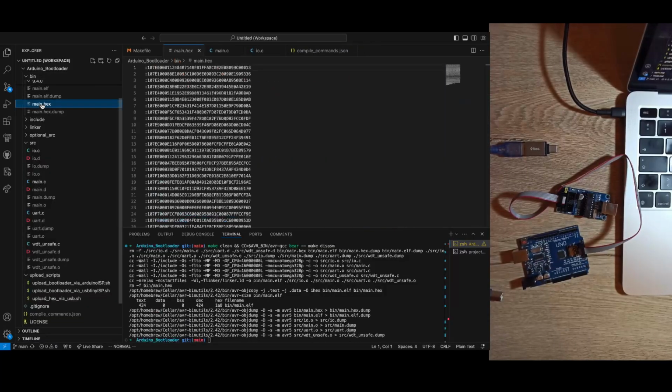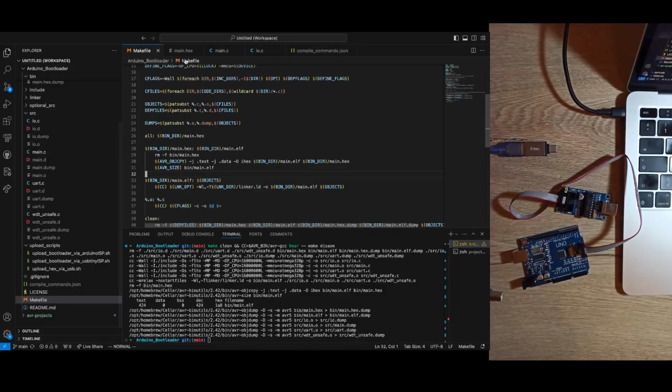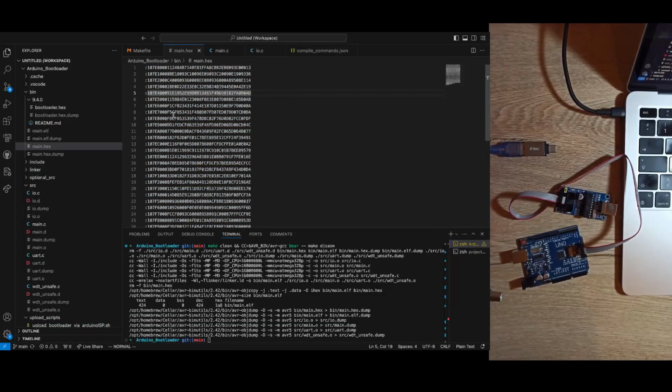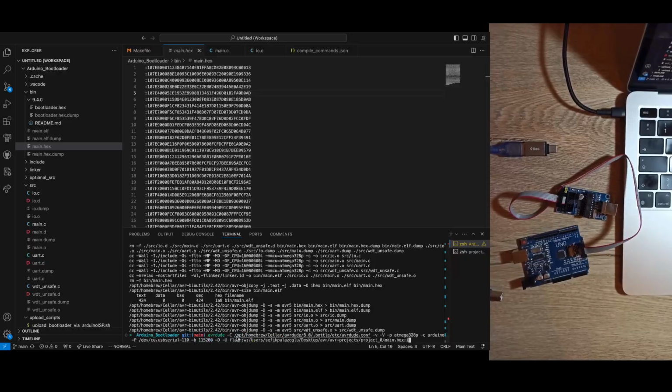If you open this, it's actually a readable one, and it's got binary data here, all of the instructions in Intel hexadecimal format. And AVRDUDE understands this Intel format. We used it in this command, right? We flash-wrote a program called this with the format Intel hex.